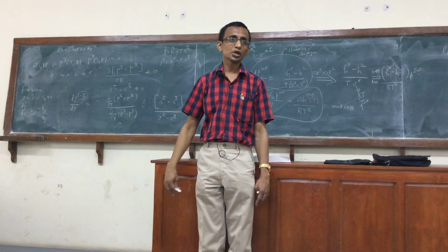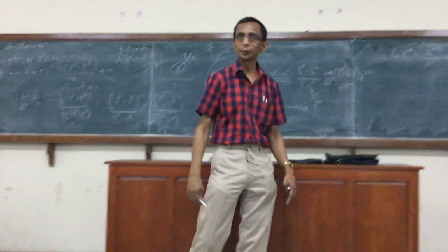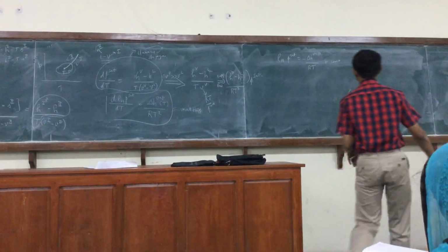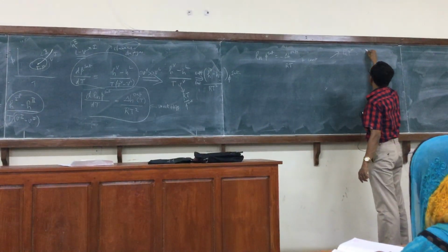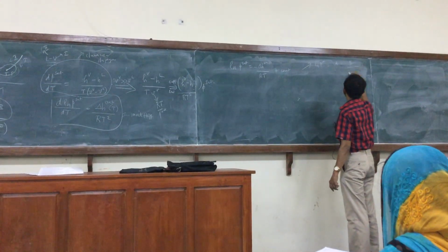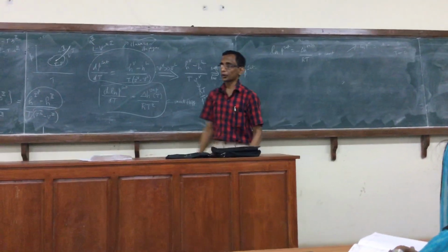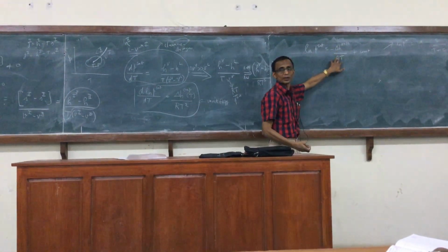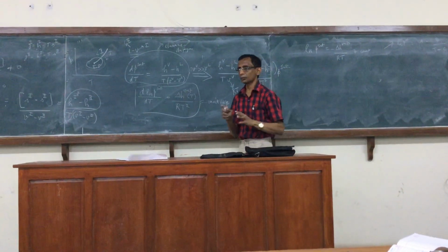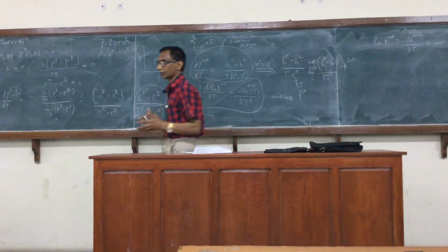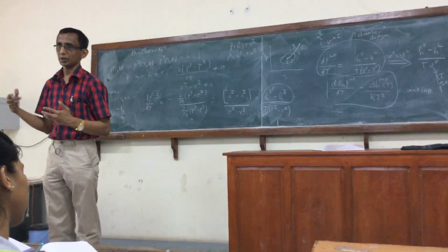These are usually fitted to a certain form called the Antoine's equation. It usually looks like this. So the form of the Antoine's equation clearly follows from this. Logarithm of P is inverse of 1 over T, but some additional constants have been added so that the fitting is done efficiently over a temperature range.